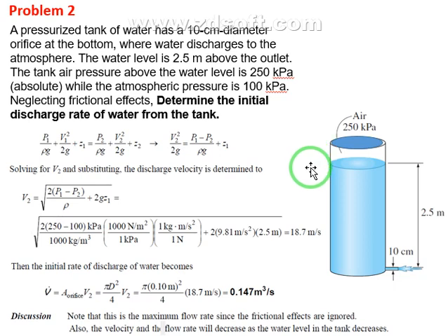So what we're gonna do, look at the answer here. We will have case 1 and 2, so we're gonna keep P1, which is equal to 250 kilopascal. We're gonna keep P2 here, which is like atmospheric pressure, guys. But same as we did before, this V here is gonna be 0, and we have velocity here, so that's fine. So we can calculate the volumetric flow rate very easily.